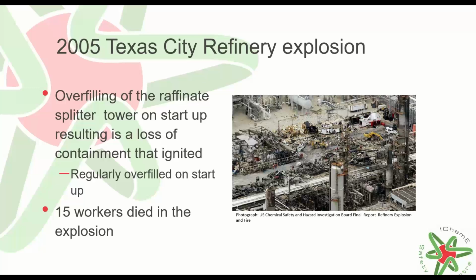And the reason for this was because the operators had experience of when it wasn't overfilled, they would sometimes have a low-level impact occur that would cause cavitation in the pumps. So in an effort to overcome that issue and try and anticipate that issue and prevent it, they would regularly overfill on startup. So again, they made the assumption and they normalized that overfilling was okay because it was done on all startups. And in fact, it wasn't the first instance of hot raffinate